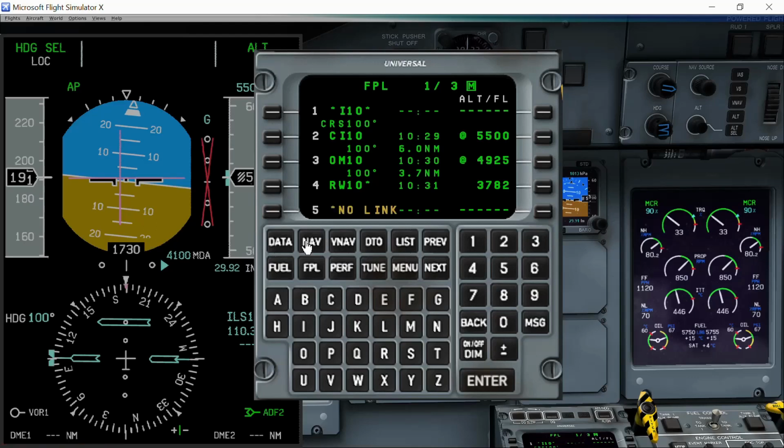Okay, because now you're on radar vectors, so you are not following the LNAV profile. But for situational awareness, to see where your aircraft is in relation to the runway, you extend the center line, which is a proper phraseology to be used. So to do that, here's what we do.